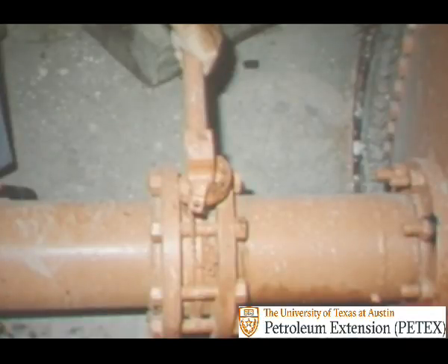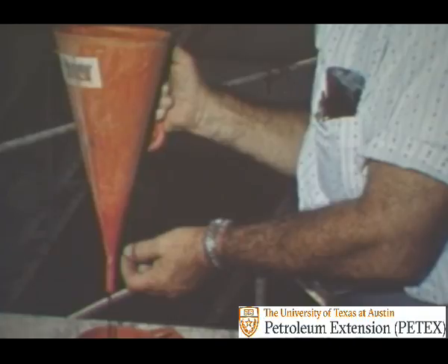Once the proper amount of calcium chloride is dissolved in the water, this brine solution is turned into the tank containing the oil. To make a good stable emulsion, the water is added slowly to the oil with vigorous stirring. Tests, like this funnel viscosity measurement, are run as a check to make sure that the oil mud is properly emulsified and has the desired properties.